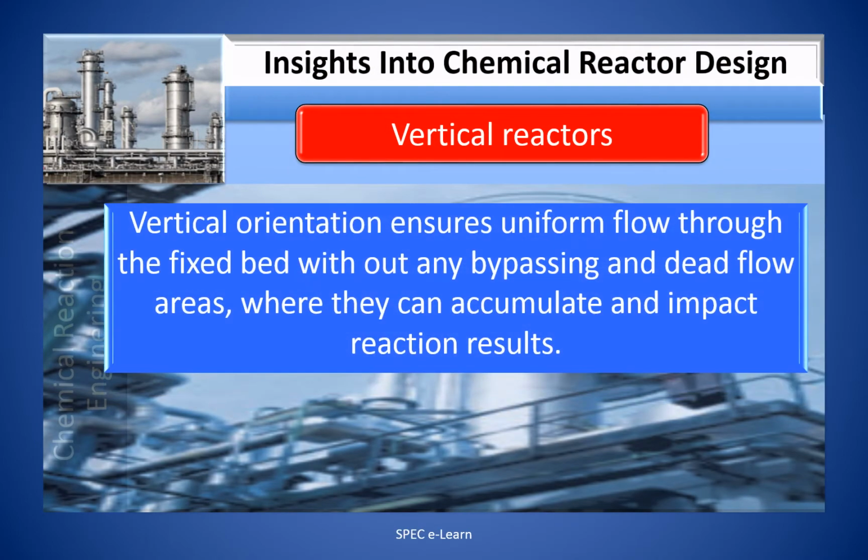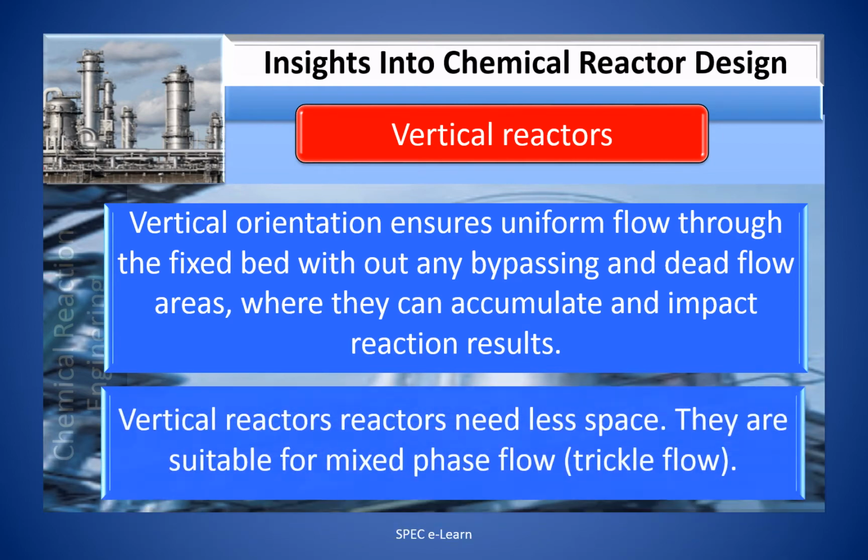Vertical orientation ensures uniform flow through the fixed bed without any bypassing and dead flow spots where they can accumulate and impact the reaction results. Vertical reactors need less space. They are suitable for mixed phase flow like trickle flow.